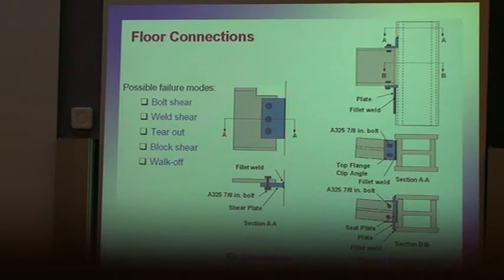Thermal expansion played a huge role in this analysis. When you have beams heating up, that would put these bolts, for example, in this type of shear connection, what we call a thin connection or shear cap connection, under stress. This is an elevation view and this is a plan view. These will be subjected to lateral loads, and we need to model how the bolts fail, how these plates and the welds and bolts and everything fail under lateral loads as well as vertical loads.